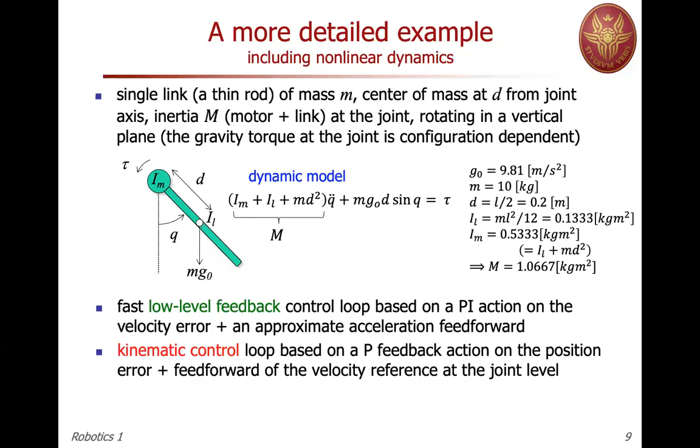Remember, the commands are always in the joint space, in order to bring this error to zero. Okay? The nominal commands are exactly the output of our trajectory plan. And we mentioned that this type of kinematic control, which neglects any mass or inertia distribution of the robot and just looks at the kinematics of the robot, is performed by closing an error either in the Cartesian space or in the joint space.